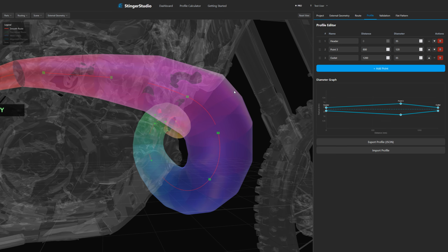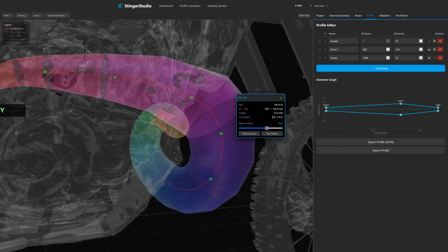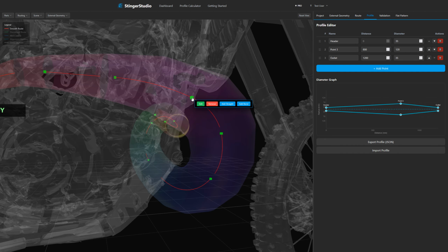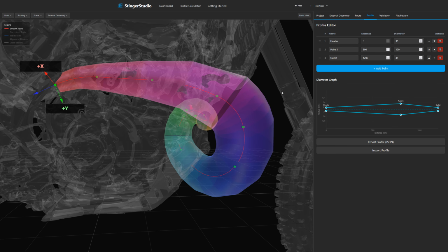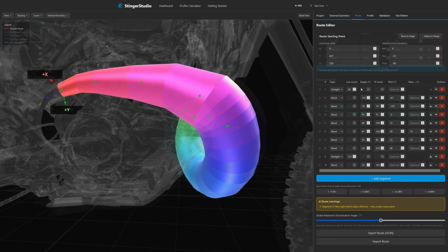In this case, these two pieces of bends around this part are determined by this route section, and we can adjust a smaller discretization angle value to it, whereby we get finer angles there. We can adjust angles separately for these route sections here.